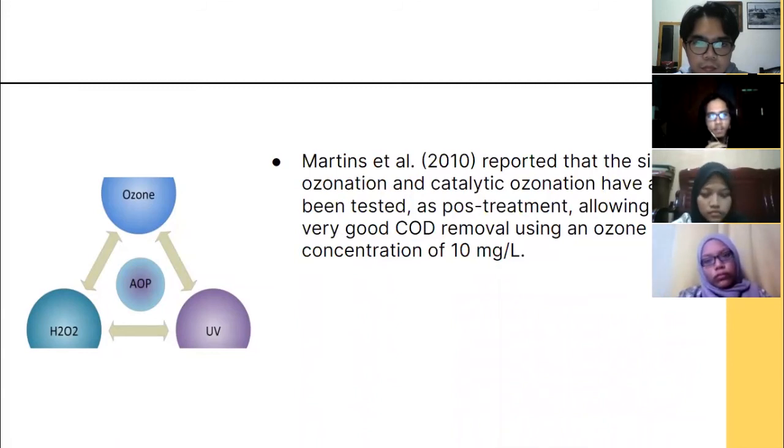Next, in research studies, Martins et al. 2010 reported that single ozonation and catalytic ozonation have also been tested as a post-treatment, which allows a very good COD removal using an ozone concentration of 10 milligram per liter.